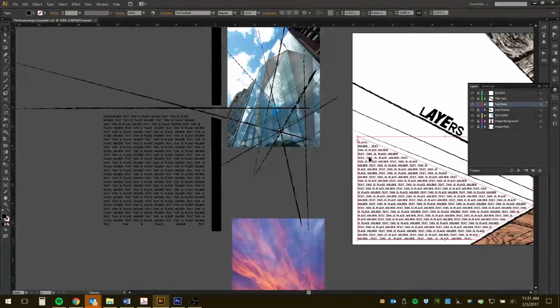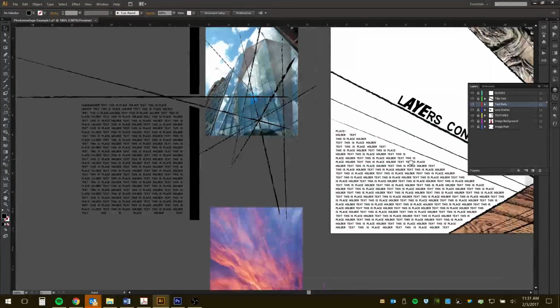You have to be careful when you're using your space bar with the text tool, because if I'm in here and I now hit my space bar for a pan, it's going to start spacing in the text, right? So I have to make sure to go back to my toolbar here, selection tool, select away from that, now I can pan around.